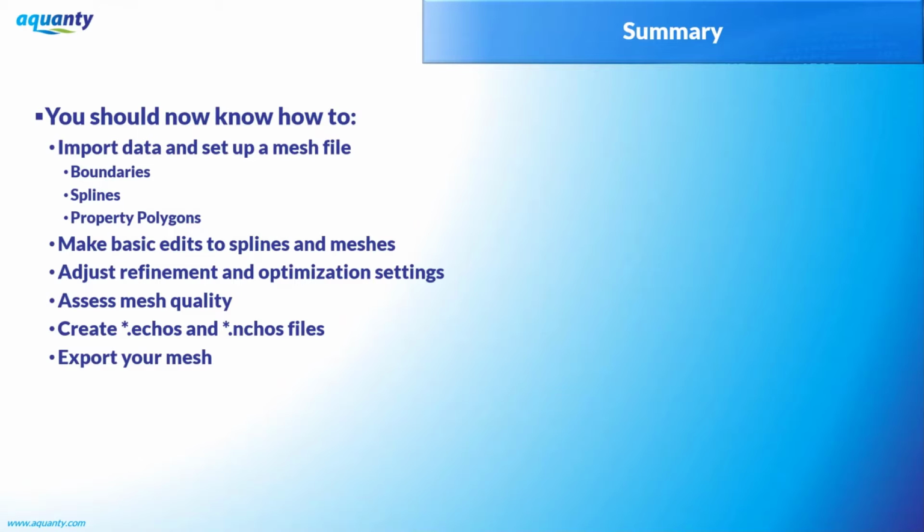There is always, of course, the ability to mix and match the different techniques as well. So you can use a polyline to select all the nodes along the boundary, and then, I think, if you hold control, you could then deselect some of those nodes. So you can mix the manual as well as the shapefile-informed selections. But if you're wanting to select all the nodes along a polyline, it's not going to select nodes in just one region. It will select all of the nodes along that polyline. So if you wanted to select only the nodes in a particular area, then just create and import a polyline specifically for that selection.